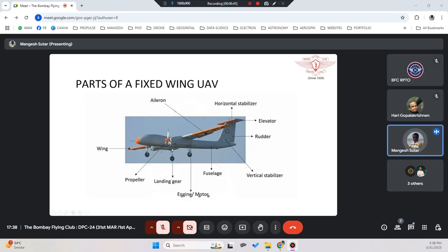So you will see on the belly of the fuselage payloads attached to it, with cameras or lidars or thermal sensors. Different devices would be there. Then on the back side you will have a vertical stabilizer, the tail portion, which has the rudder, but your horizontal stabilizer is not at the tail portion, or at the tip of the tail. It is on the upper side.